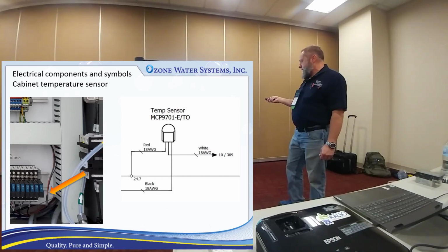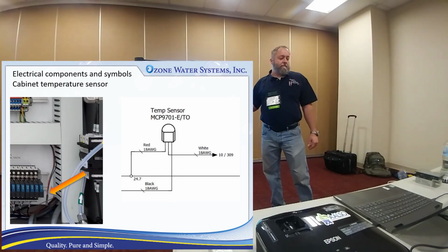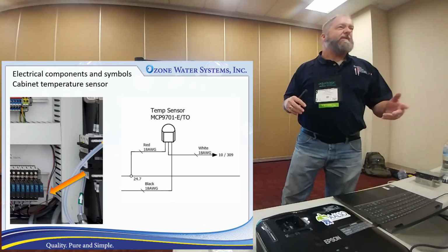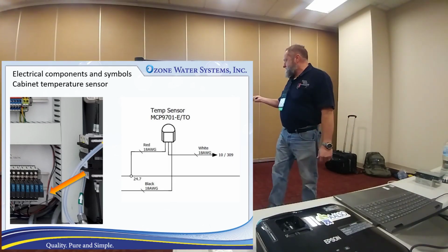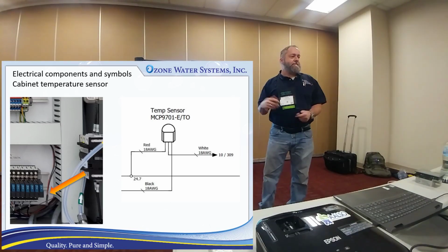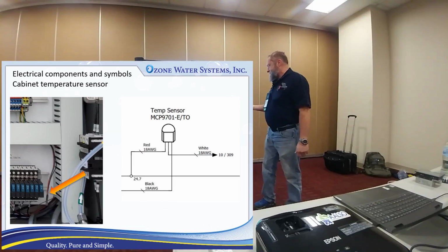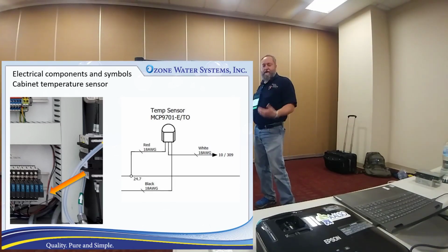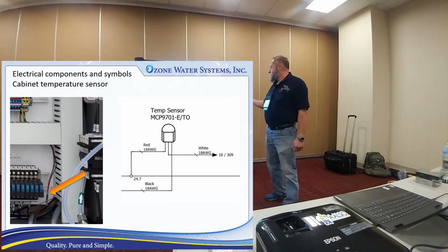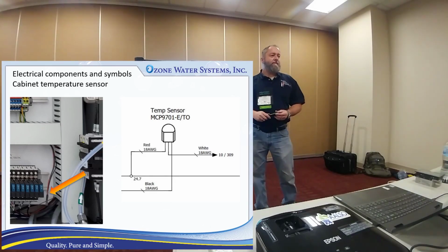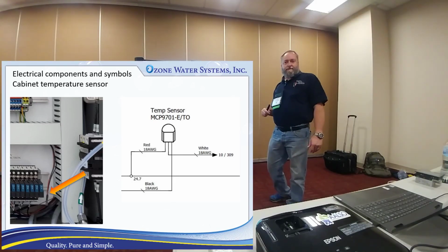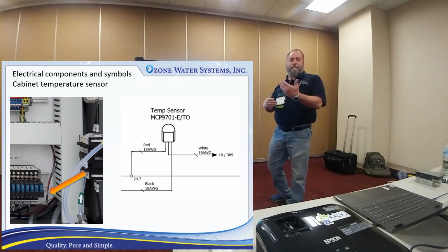Briefly on this one, this is our analog signal coming out. If for some reason that sensor fails and it's reading too hot, you can actually disconnect that wire and it'll just go blank on the actual input, because we've got such triple redundancy on the temperature. It's not going to be catastrophic if you lose that while you get it fixed. If it's faulting as soon as you turn it on, and the thing says 150 degrees or something because that sensor's failed, you can just pull that wire out, and we could walk you through that on the phone. With such high redundancy on the temperature monitoring, it's not catastrophic to pull that out while you get a replacement sent out.